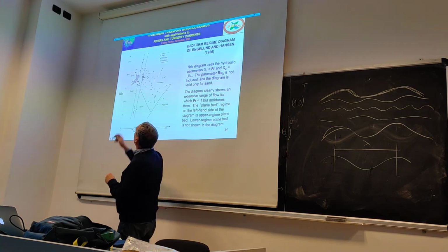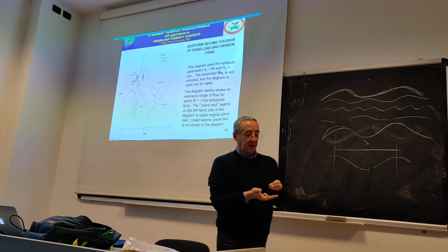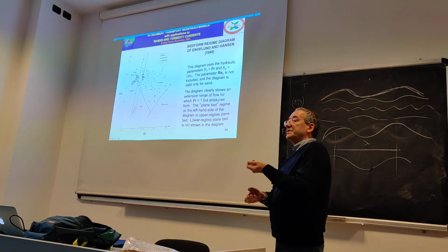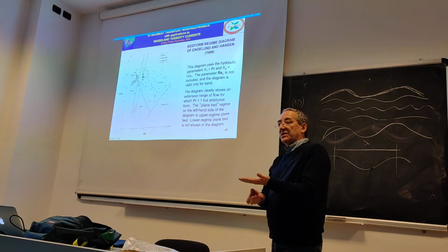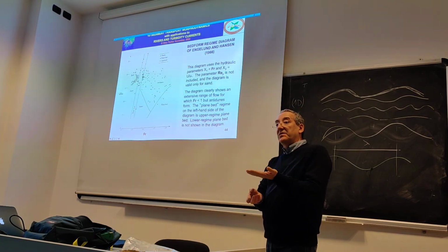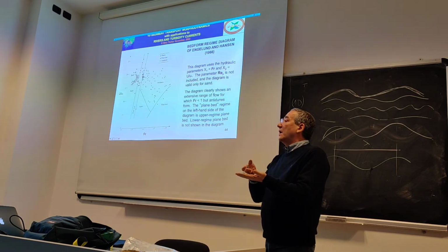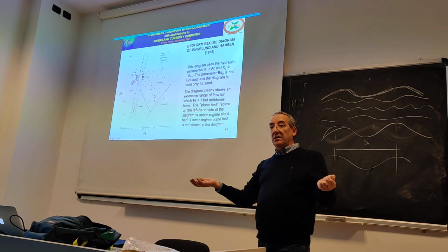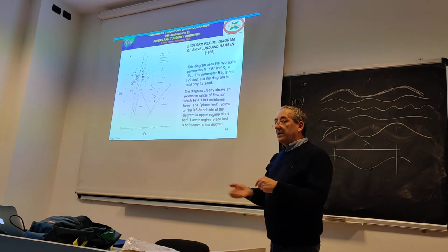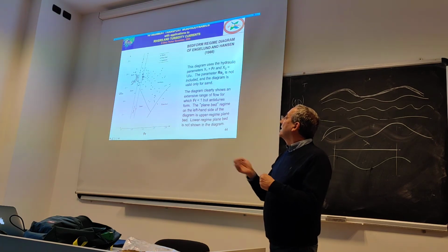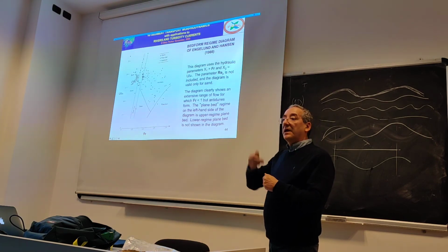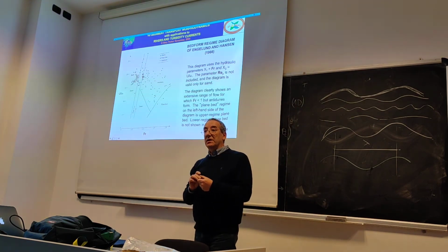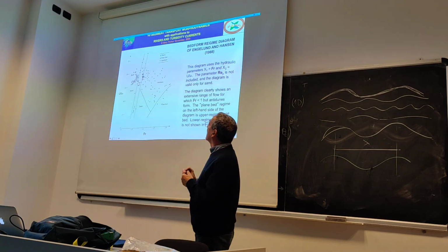This one is something in between the formation of dunes and anti-dunes. So when you increase the Froude number, you will start to see the formation of dunes, and then at some moment they will disappear, and you will have a plain bed solution. So the uniform flow, in a sense, is stable. After a stable uniform flow, if you increase the Froude number further, you will have the formation of anti-dunes migrating upstream, backwards.